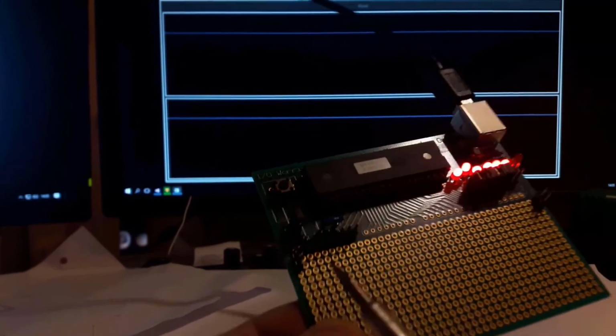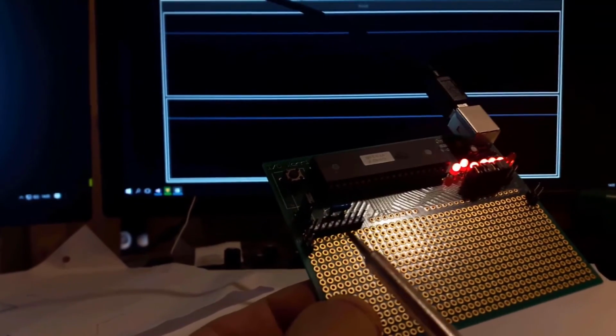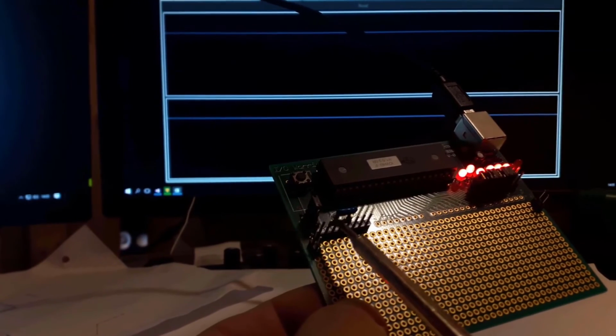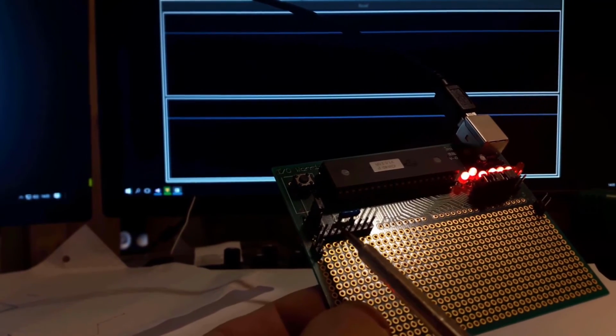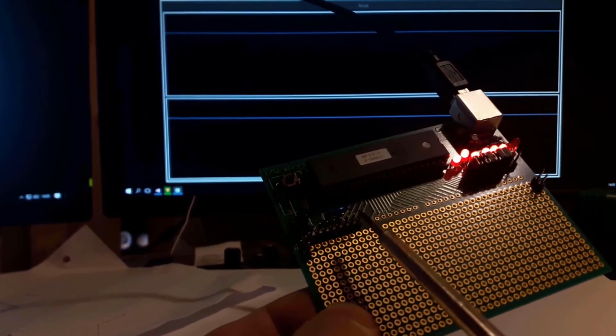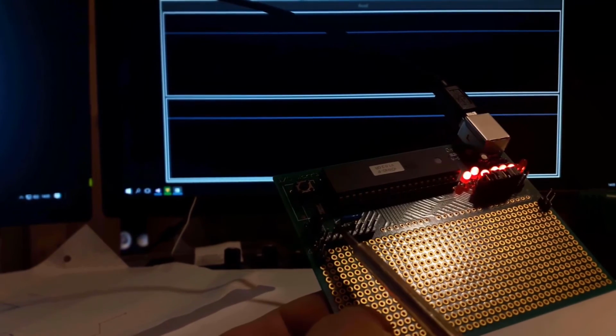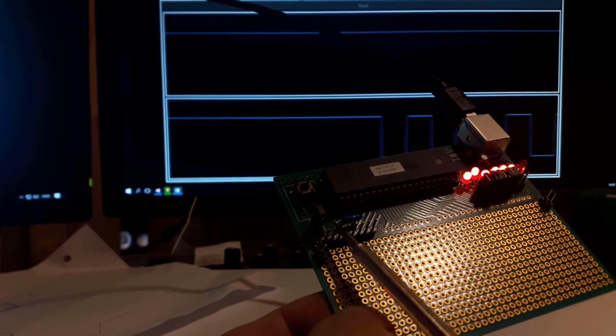To test the MasterWriter's cycle matching feature, I've modified the backend to constantly read high cycles as if it was reading an infinite number of bytes. The data line pulldown is attached to this GPIO pin, so I can take the role of a slave with a screwdriver. As usual, the MasterWriter will try to match incoming cycles, which will be printed to the console.